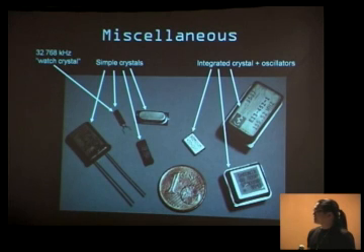If you see a crystal in this kind of package, you almost always can guess its value. It's around 32 kilohertz. It's the traditional watch crystal, so to speak. And most of them have a value printed on the case. Crystals are interesting because if you're trying to do clock glitching or time hacking on a device, you want to look there first to see if you can override. The crystals themselves actually have a very weak signal, so if you just put a function generator over it, you can directly override the crystal just by putting a signal right over that. You won't even have to remove it.